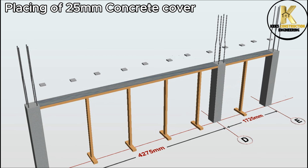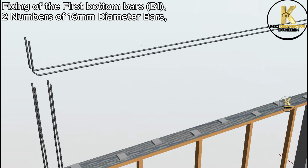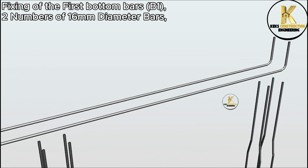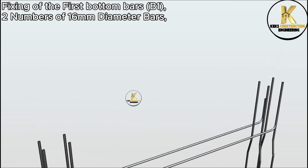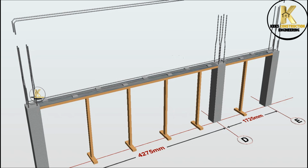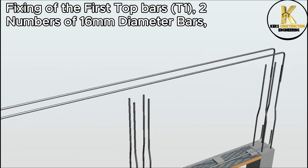Placing of 25 mm concrete cover. Fixing of the first bottom bar, B1, 2 numbers of 16 mm diameter bars. Fixing of the first top bars T1, 2 numbers of 16 mm diameter bars.